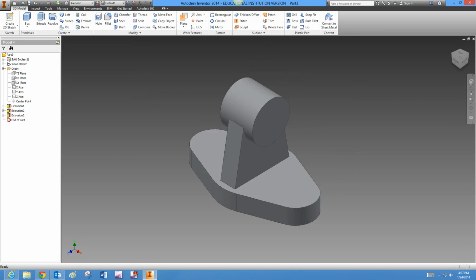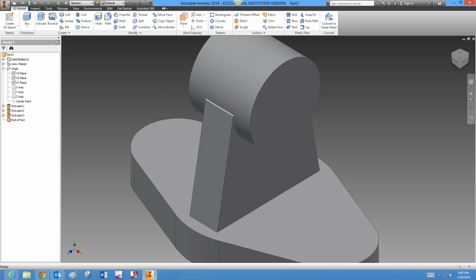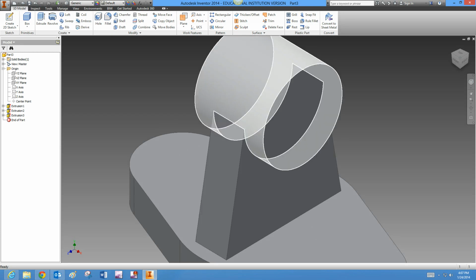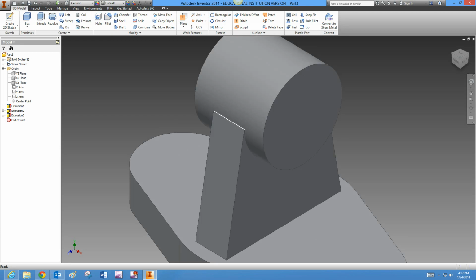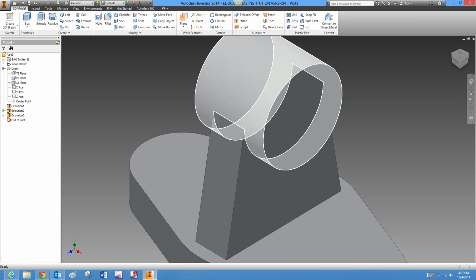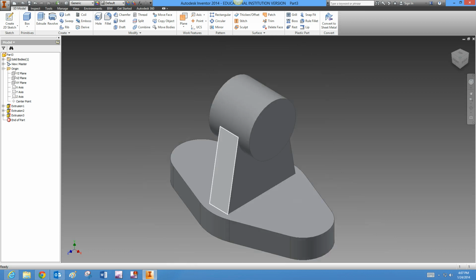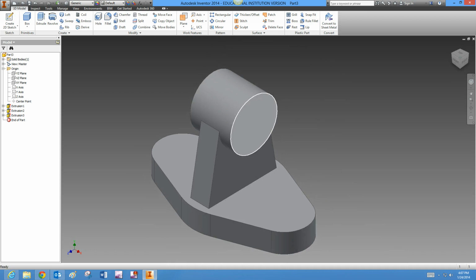Okay, now I want to stop here. I want to point something out. Now notice in the book that we have an edge right here. Now a lot of times when you see a flat plane going into a cylinder, this edge will not be there. That is when the plane is tangent to the cylinder. In this case, we have an edge created here. All right. Now we're not given a dimension for that edge, so I have to assume that this edge is even with the center point of the cylinder.